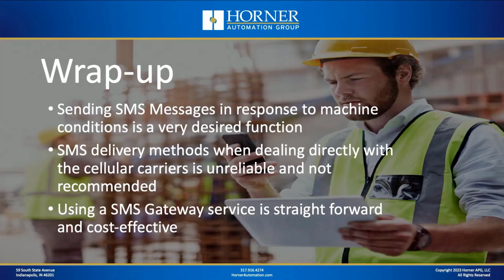Let's go ahead and wrap up our topic for today. So sending SMS messages in response to machine conditions is definitely a desired function, because we know these days people respond to text messages quickly. Okay, and seeing that those messages are reliably delivered, we think that sending emails to the cellular carriers directly has proven to be not reliable by our experience in the past, but SMS gateway services are reliable, and we do recommend those if this is the direction you want to go in terms of sending SMS messages from a machine.